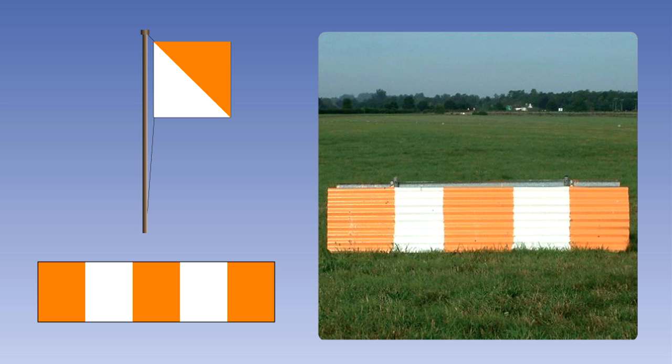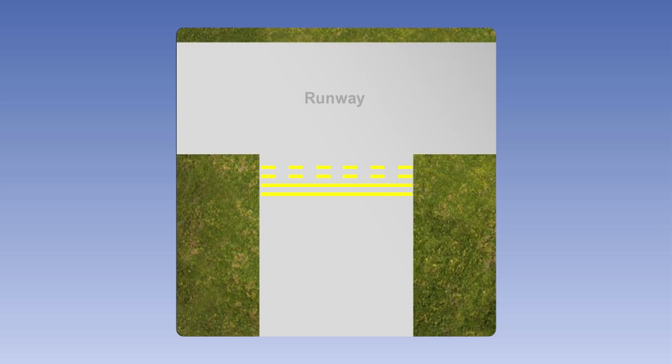There are two styles of runway taxi holding position marking, patterns A and B. A pattern A style runway taxi holding position marking consists of two solid and two broken lines laid across the entire width of the taxiway, and normally at right angles to the taxiway centerline, the broken lines being closer to the runway. A pattern B style runway taxi holding position marking consists of a ladder mark laid across the entire width of the taxiway, and normally at right angles to the taxiway centerline.